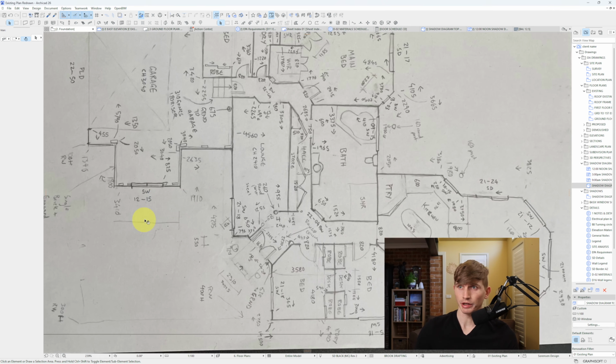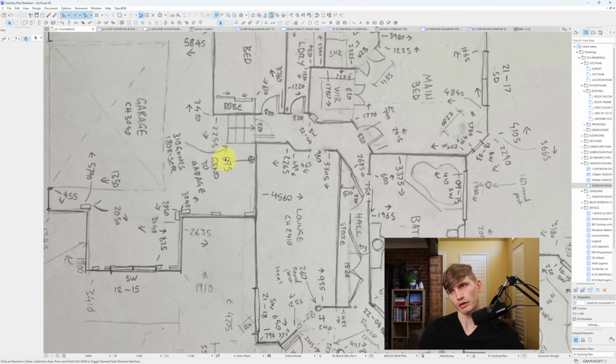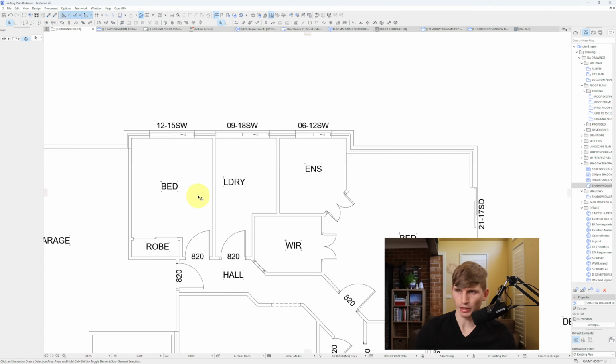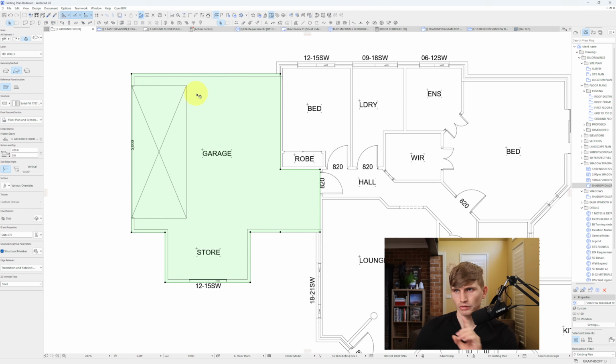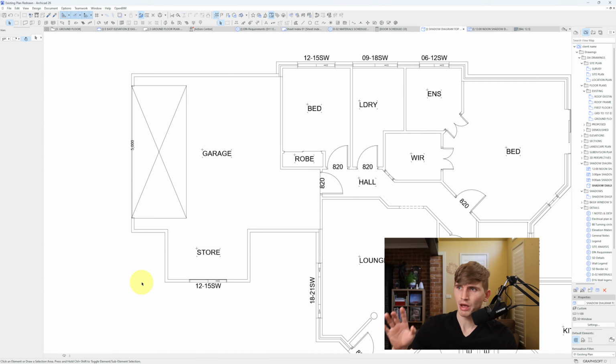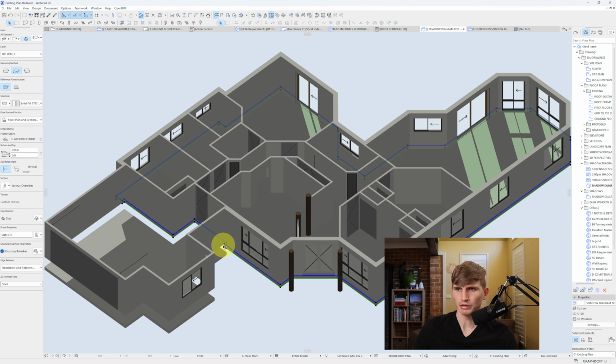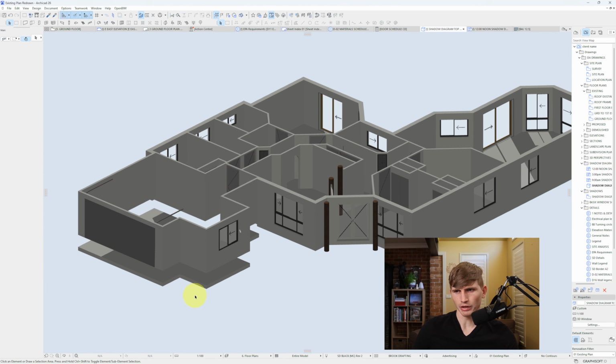And if I go down a story to my measure up, I'll just have this measurement here, 675 ground to garage. So that's the height difference between the two. To do this, I'll just go back up to the story and I'm going to select the slab that we created and I'm going to go minus 675 and I'm going to go enter. Nothing appears to have happened here on the screen, but if we go into our 3D again, double click, we'll notice this one has moved down.